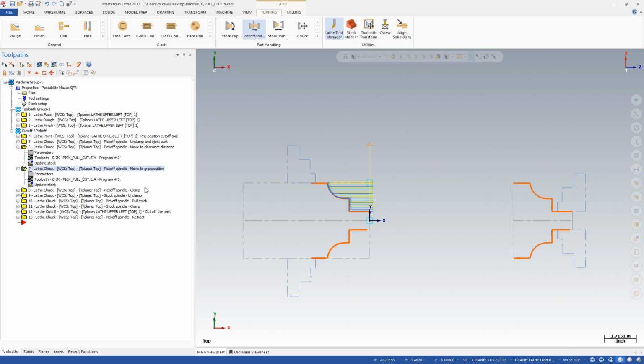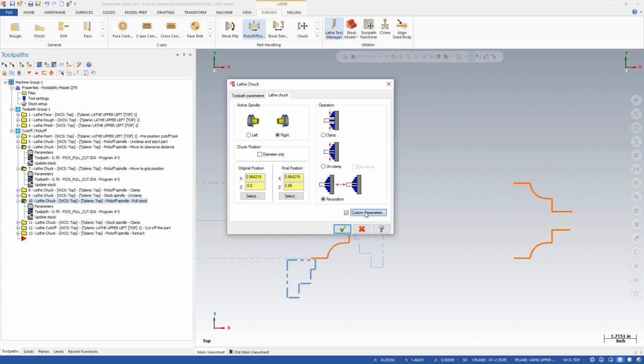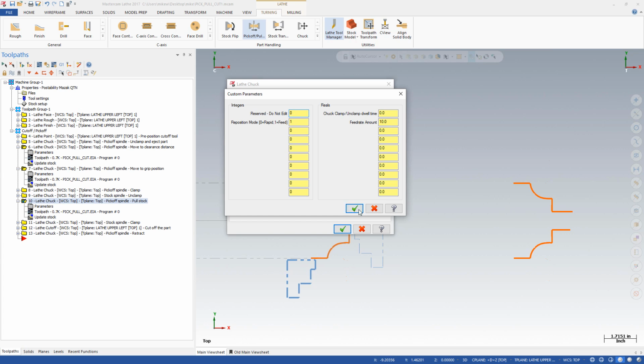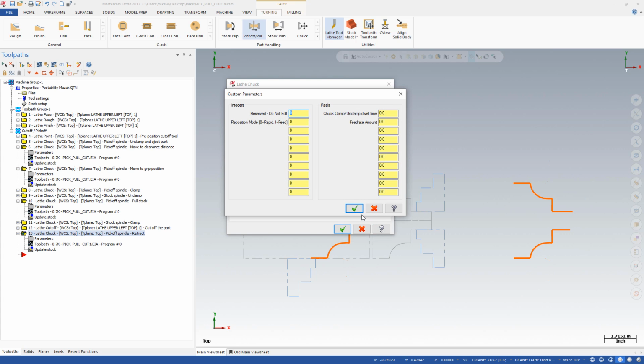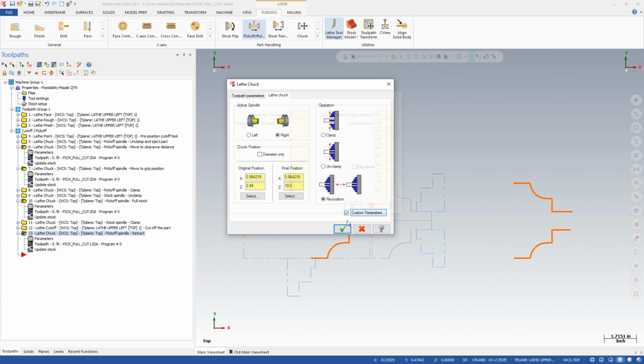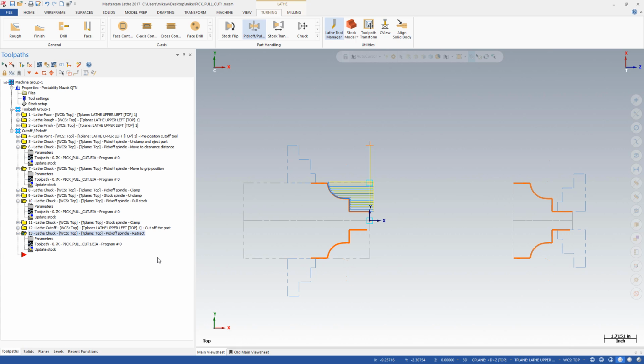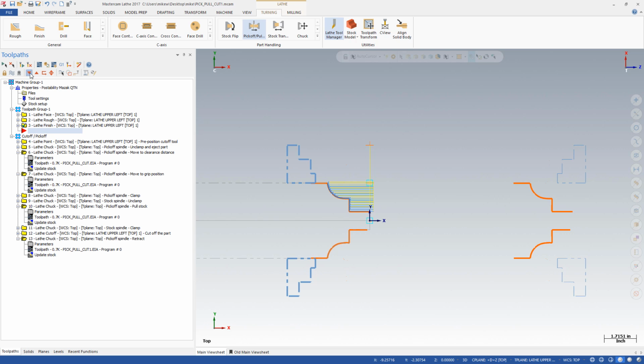Op 10 is the bar pull, and it too should be a feed motion. Last is Op 13, which is the subspindle retract, and that should be a rapid move. More checking can be done in backplot or by moving the operation arrow.